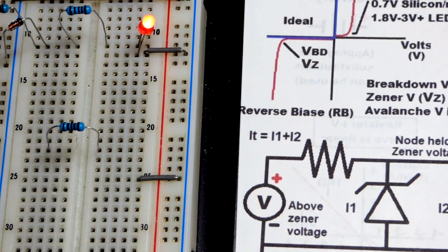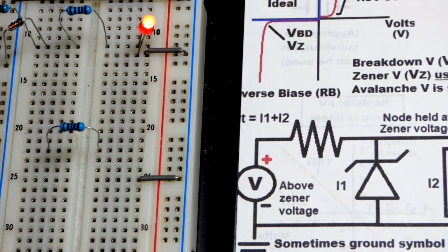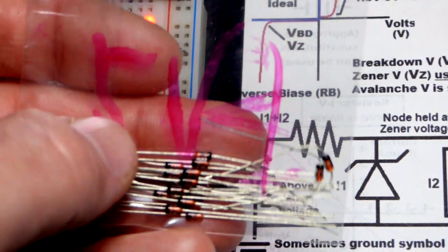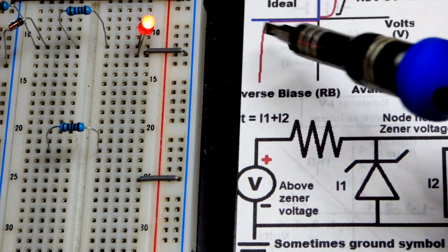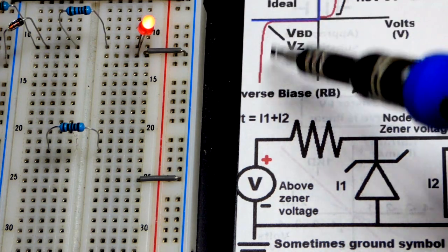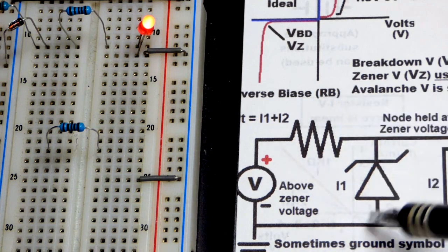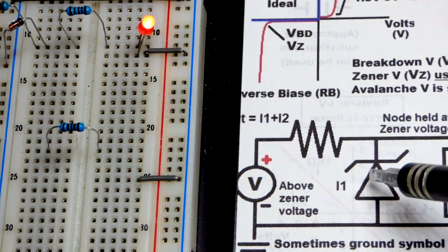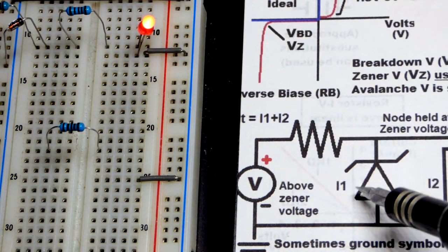The Zener diode, you actually select a voltage. They come with voltage settings, so that's why this bag has 5V1 on it. That means 5.1 volts. The Zener diode I'm using is rated for 5.1 volts. Reverse biased, it will start conducting at 5.1 volts, and it's safe for it to conduct. You still have to limit current through it. It has, I think, a half a watt rating. I'm not sure though, but it has a wattage rating like everything else. You have to limit the current going through it.